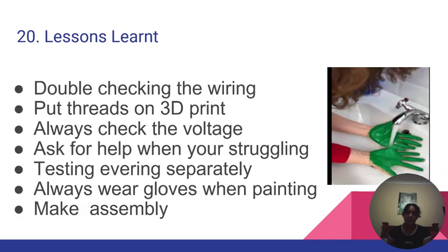And the lessons I learned: double check the wiring, because if you don't, it's just going to fall out, and rewiring it is not fun. Put threads in a 3D print, because it's not fun when that has to happen. Always check the voltage, because you don't want to blow something up or electrocute yourself.